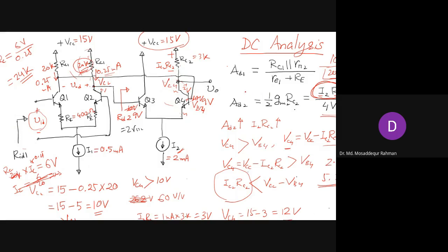Right? So if your bias current is lower than the load current that is needed, then again your amplifier will fail. Right? It will not work over the whole range. It will go into cutoff if it is not able to supply that maximum amount of current. So that also has to be considered while you are designing your amplifier. So besides the voltage, you also need to consider the current, so that it is large enough to supply the current needed by the load.